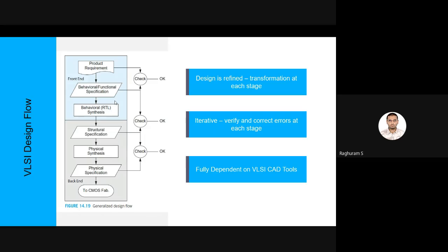But like I said, Verilog gives you something from high level programming languages that gives you the case statement. Okay, so the case statement itself is not so great. The real greatness is that there are a lot of tools which can perform what is written here as behavioral synthesis, which means that we can take that case statement that you have written and feed it to some tool, and that tool will convert the case statement where there's not even a single gate level description into a complete gate level description, okay, in terms of our digital gates.